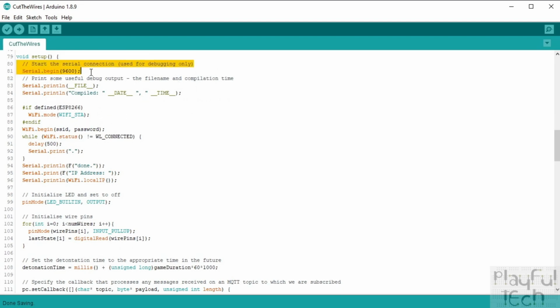We're using that to output some information. And this is something which I think I've used in some projects, but I should probably get more consistent at using it. So there's a couple of predefined variables you'll get in every Arduino script. In fact, everything that's gone through this particular compiler gets it. So __FILE__ with double underscores either side like this.